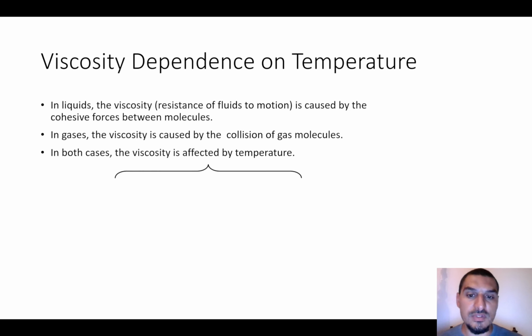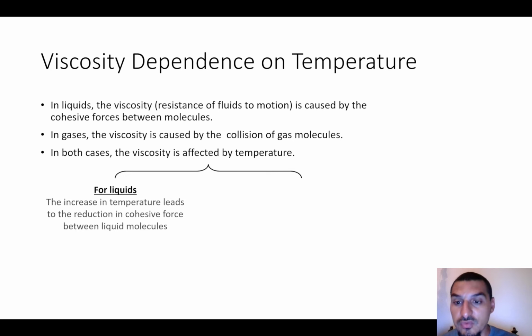The reason of viscosity in liquids is different from that in gases. For liquids, and this is something we mentioned before when we saw the video of different liquids that were poured at the same time for the same distance, we said that the viscosity is due to the cohesive force between the liquid particles or the molecules. And as the liquid molecule cohesive force increases, the viscosity increases, because it's going to be more difficult for the molecules to slide over each other.